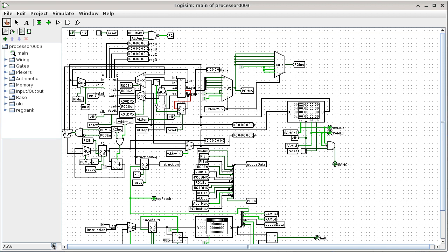Okay, so if you use Logisim to analyze this circuit, it has a lot of tools to help you to do that. When you're using the poking tool, which is already active, you can poke a wire and it will tell you where that wire goes, what that node connects to. So it's a great tool, because if you just want to figure out where does this connect to, what else does it connect to, click on the wire using the poke tool, and it will highlight everything that connects to that particular node or net. Depending on whether you're doing board layout or schematic capture, they're termed differently, but it's basically the same thing, the same electrical connection. Is that okay? All right.